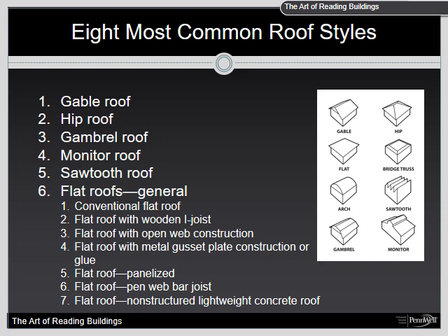often making it difficult to determine which type and or method of construction has been used. A variation of a flat roof is a shed roof, which is nothing more than a flat roof that has been constructed with a pitch that exceeds 10 degrees. A low pitch is defined as 10 to 20 degrees, and most sheds are constructed with a pitch exceeding 20 degrees.